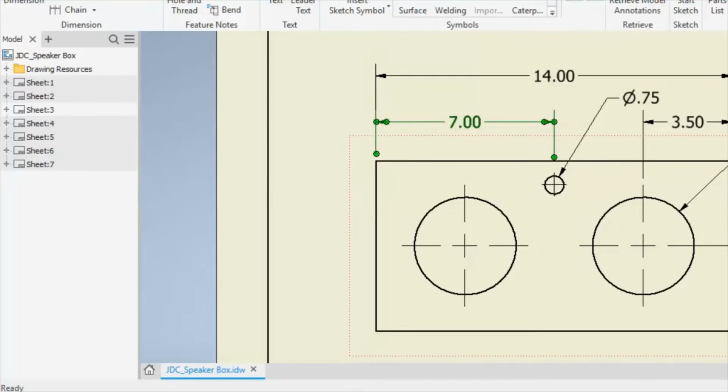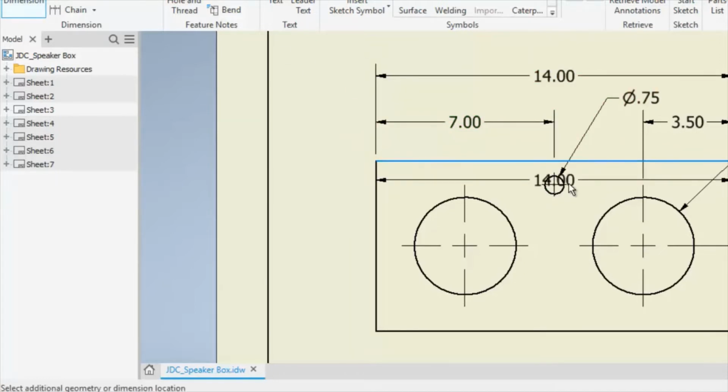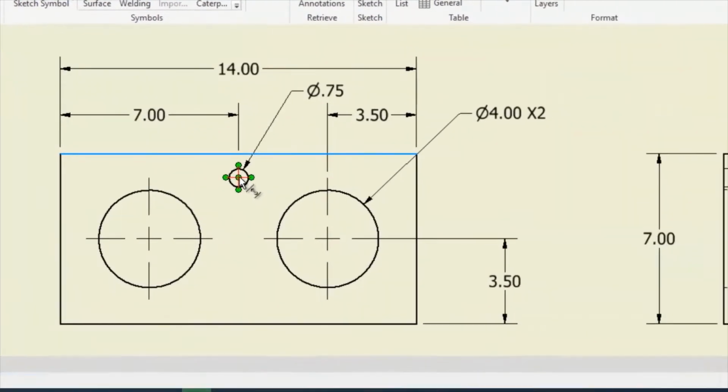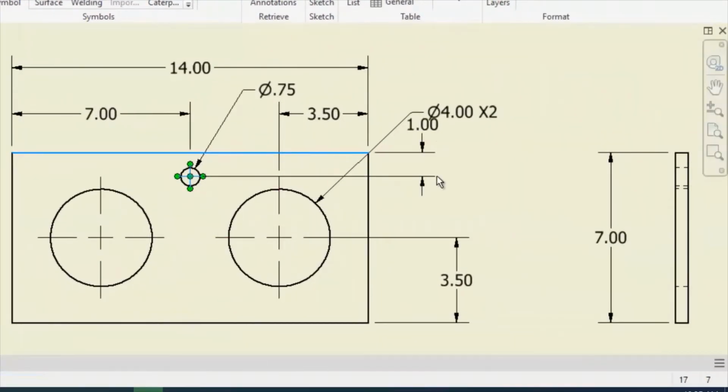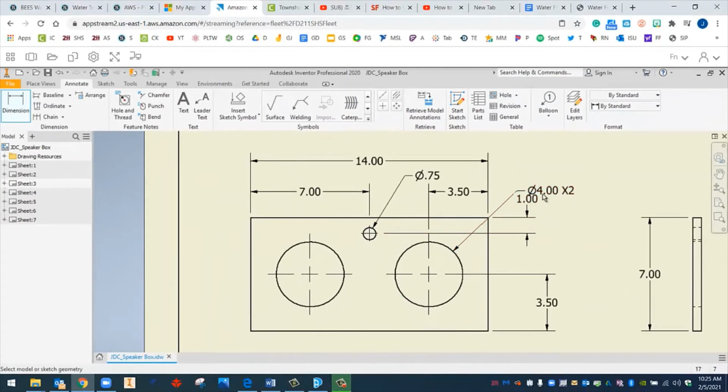We also have to locate the height of this. We can do that a couple of different ways. We could click on Dimension, from here to here, and that dimension is 1. If we do include something like that, that is fine. But we can see that these dimensions right here are a little too close, so I might need to modify the location of this radius one.